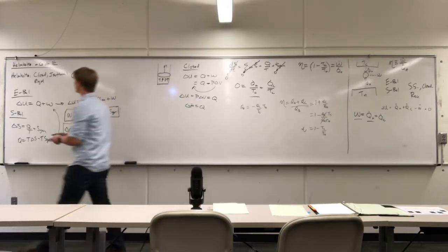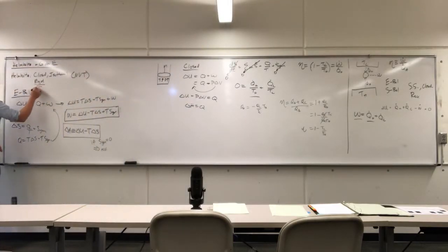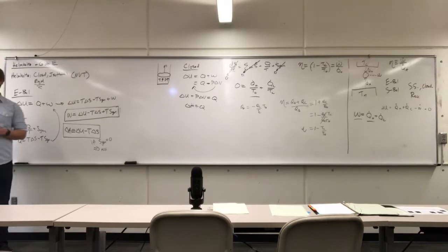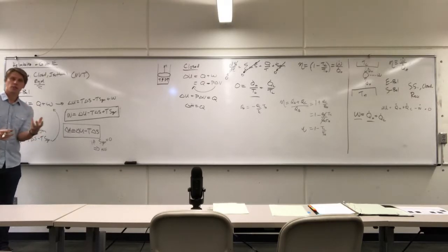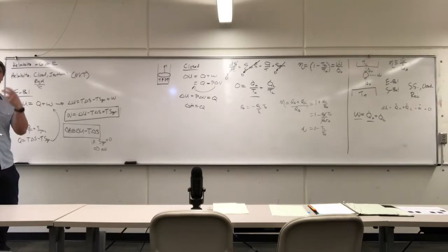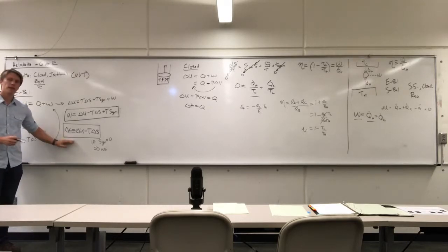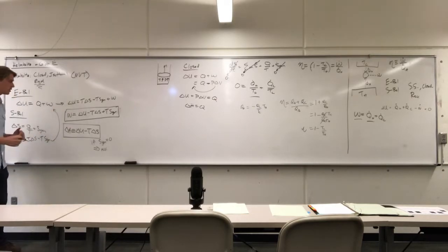Because in a liquid system, we oftentimes will view it as an incompressible fluid, so there's no need to add in the extra complexity of PV or pressure volume changes. In chemical engineering, we are most interested in, most of the times, vapor-liquid phase transitions for distillation. So that's why we don't generally use the Helmholtz energy, we more generally use the Gibbs energy, which we can derive in just a second.